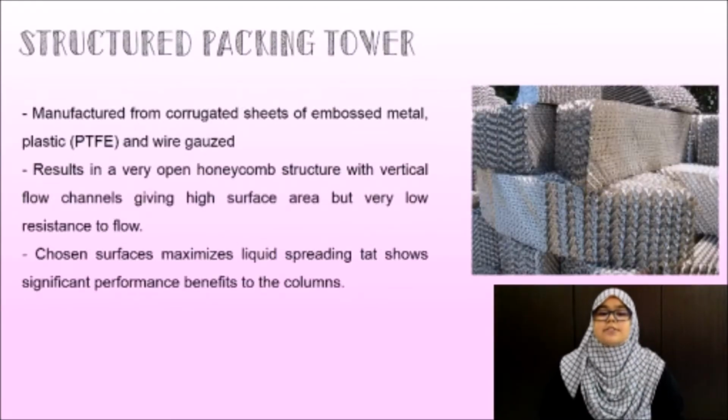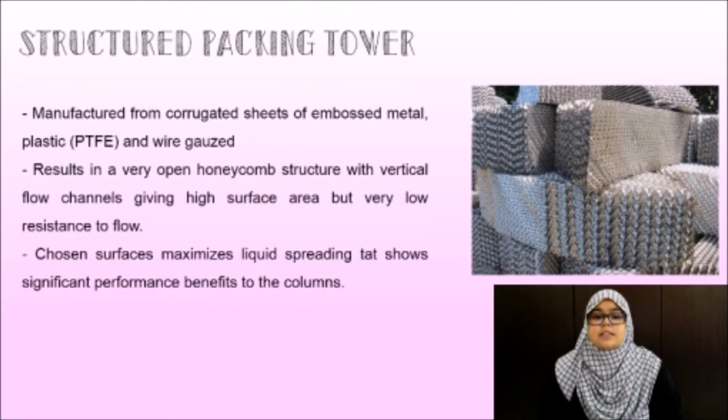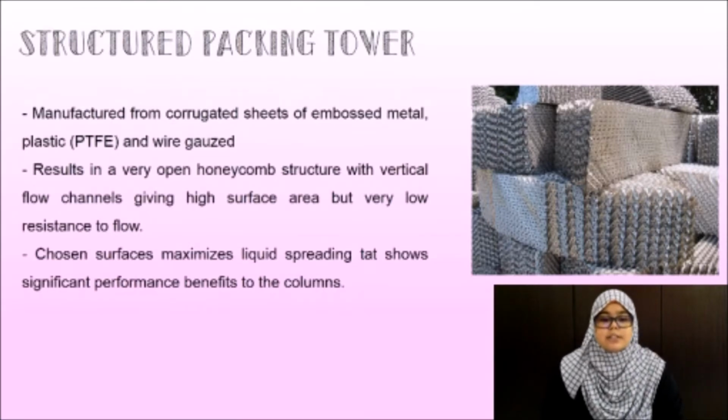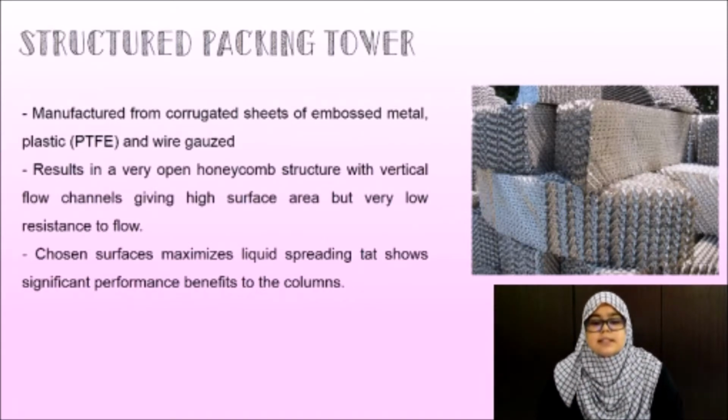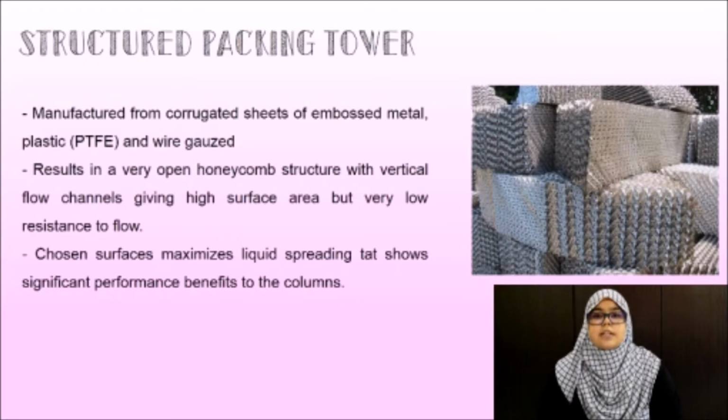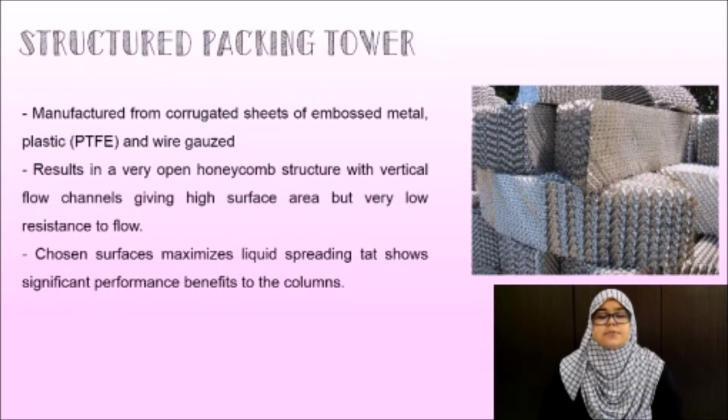The next type is structured packing tower. Structured packing tower is manufactured from corrugated sheets of embossed metal, plastic such as PTFE, and also wire gauze. This results in a very open honeycomb structure, with vertical flow channels giving high surface area at lower resistance to flow. The chosen surfaces maximize the liquid spreading, which shows significant performance benefits to the columns.